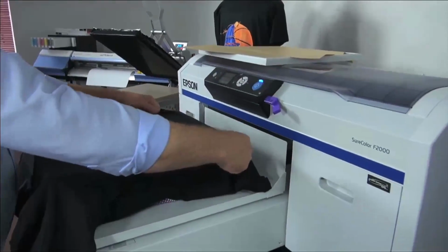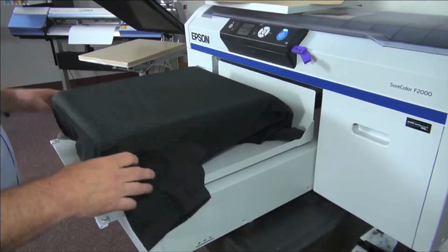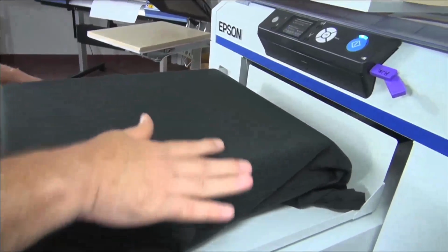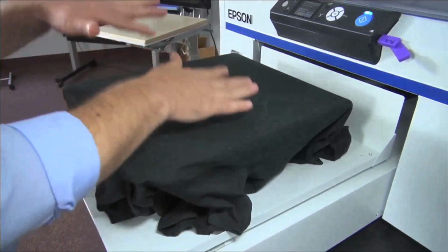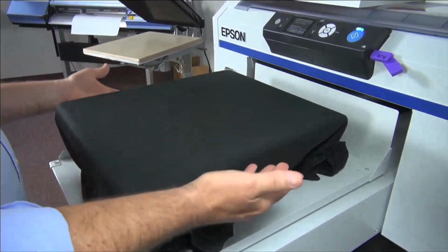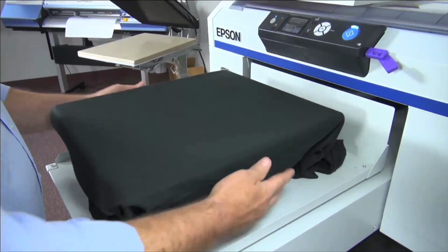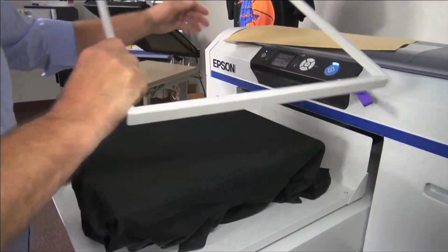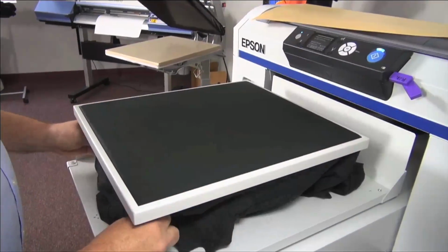Now while this is printing, I'm sure it'll be interesting to watch, but we'll go over some of the more details as we go. I like to thread the shirt on almost religiously because I like to work in one layer of fabric. If I would just lay it on top, the chances of me getting some wrinkles in there is greater, which means I can't get the shirt close enough to the print head. It will do a decent job a safe distance away, but what we like to do is get that shirt as close to the print head as possible. That's going to give me the cleanest lines, the least amount of overspray, so that I have a good definition.